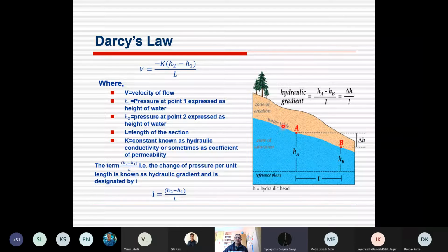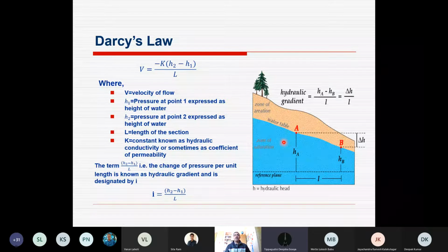depends. And finally, we can find out what is the total amount of water that is moving per unit time or per day, per month, something like that, under these conditions. So this is basically the application of Darcy law, and later on 2 more applications I will show you here. So this is saturated hydraulic conductivity, what we want to learn.